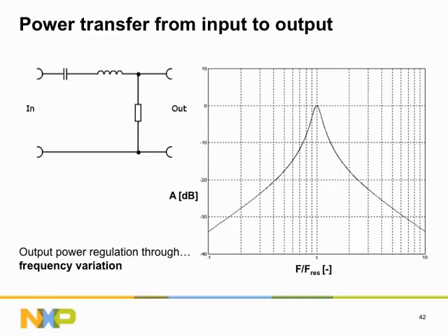Normally, an LLC resonant topology uses only the inductive side of the transfer function, the part right of the resonant peak, to control power transfer from input to output. Of course, this is a somewhat oversimplified approach of the operation of a resonant converter. But the basic idea is exactly as outlined in this short explanation.